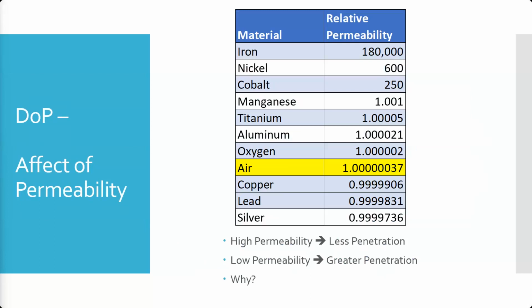But the steel, permeability and retentivity are also linked, right? So this kind of gives you that. So again, if we're working with an aluminum airplane, we're not going to be able to change the permeability. We're just kind of stuck with it. So it goes back to that equation. The only thing we can really control is frequency. And then, again, we can also control how much power we're putting through the coil and stuff like that.